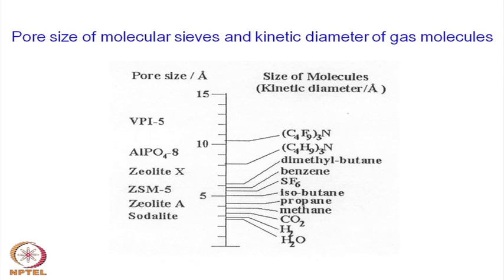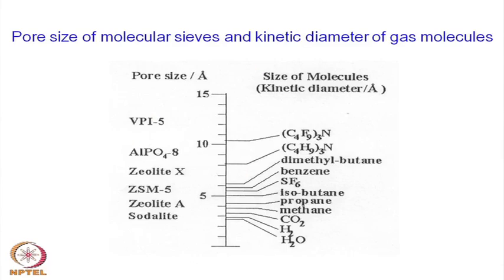So, these tunnels are good enough, in fact, they are through and through tunnels. These are generated not because of the agglomeration of the powders or consolidation of the powders, but because of the crystallographic arrangement of the atoms. The atoms are arranged in such a way that there are some crystallographic tunnels, and these tunnel sizes differ depending on the particular composition.